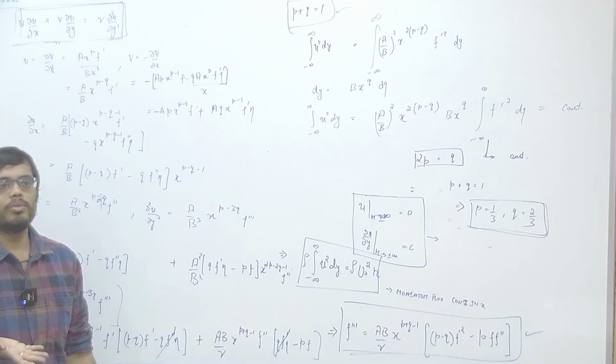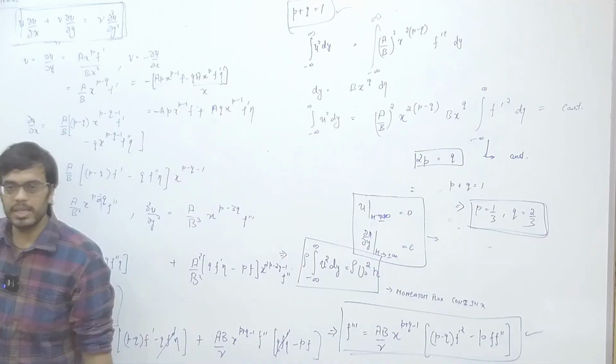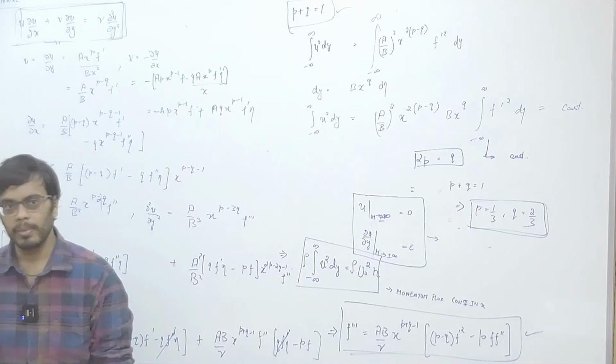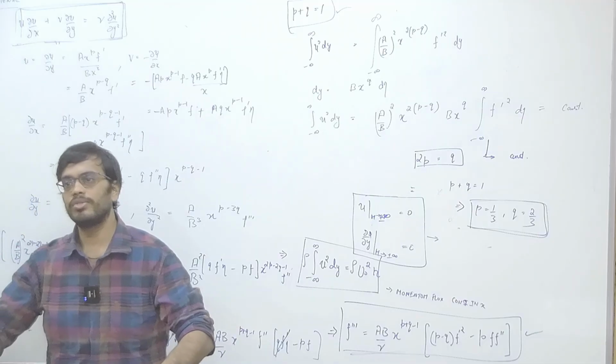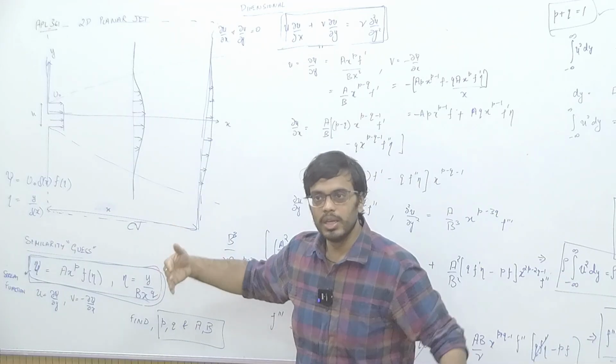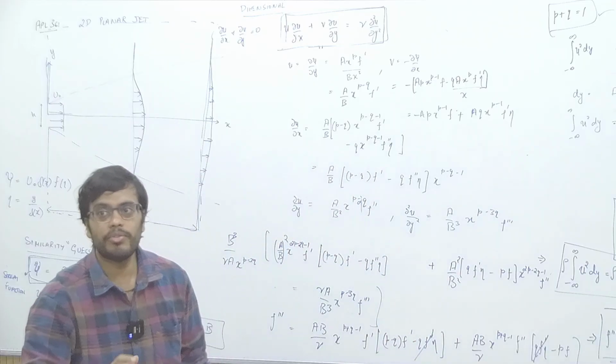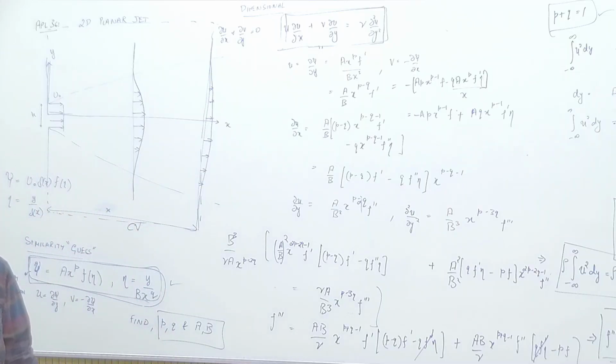So, intuitively you can think about it like this: you have, let us say, a boundary layer, and the delta is growing as a diffusion thickness as you move downstream. If it is growing faster than the diffusion, then there is some other physical mechanism helping this delta grow. What is that mechanism here? It is the entrainment of the mass flux, which we showed: there is some v velocity at minus infinity, which is getting dragged along with the jet. In your Falkner-Skan boundary layers, you will find that for different cases the delta's variation with x is different.